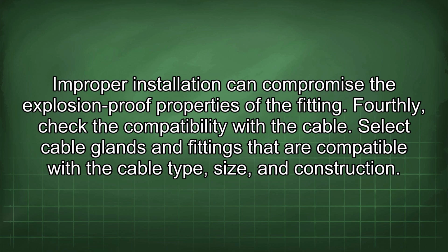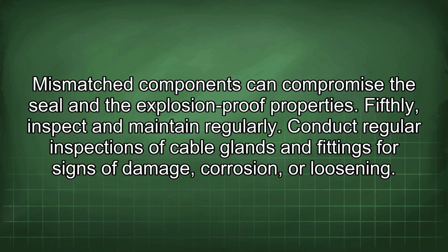Fourthly, check the compatibility with the cable. Select cable glands and fittings that are compatible with the cable type, size, and construction. Mismatched components can compromise the seal and the explosion-proof properties.